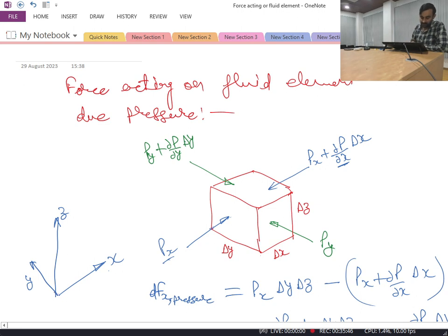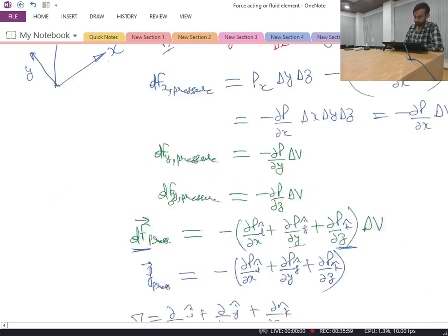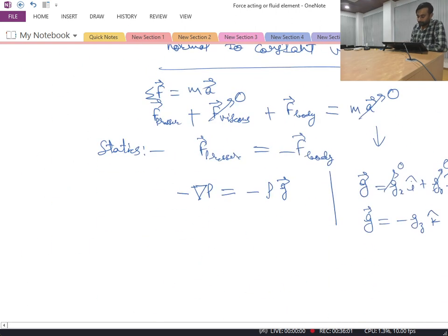As these are lying on the same horizontal plane, we have seen previously that in the horizontal direction for a fluid element, pressure does not change. So for gradient of P particularly, del P by del x will be 0. Similarly, del P by del y will be 0. So we will have only one component responsible for variation of pressure, in the z direction.